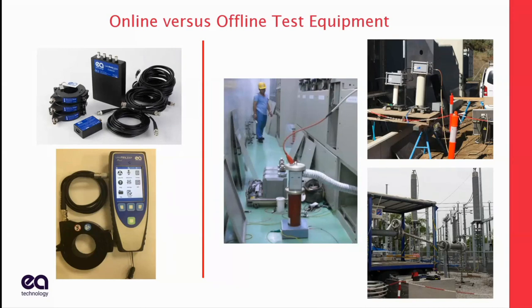So when you do an offline test, you still need to energize the cable. The cable needs to be at line voltage or even higher. And so you need to bring in equipment capable of doing that. Typically that's done with VLF test sets. They're big. They can be man portable for up to say 30, 50 kV, but beyond that, we're talking truck mount. The picture in the lower right is there's over 300 kV cable in New Jersey, and there were 3 tractor trailers full of equipment to try and energize it at power system frequency.